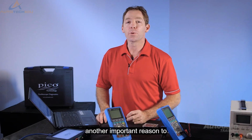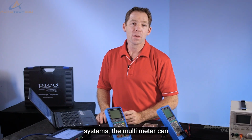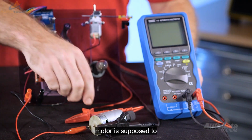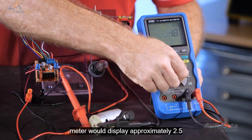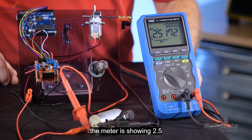This is another important reason to only use an oscilloscope when diagnosing one of these systems. The multimeter can be very misleading. This motor is supposed to be driven by a 50% 5-volt duty cycle. A multimeter would display approximately 2.5 volts. As you can see, the meter is showing 2.5 volts.